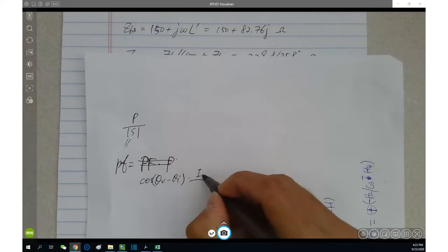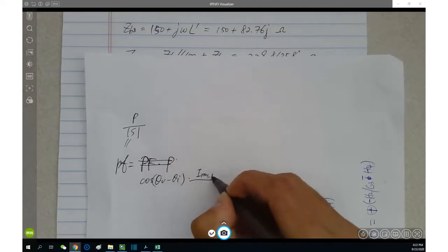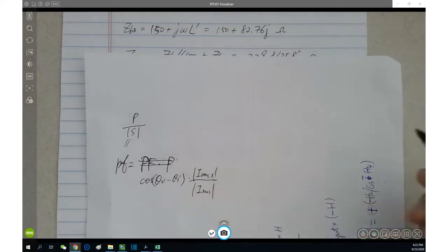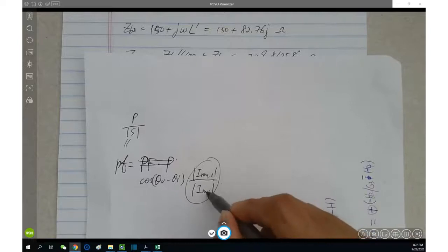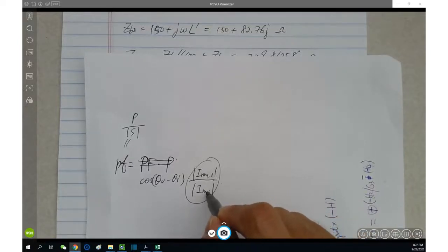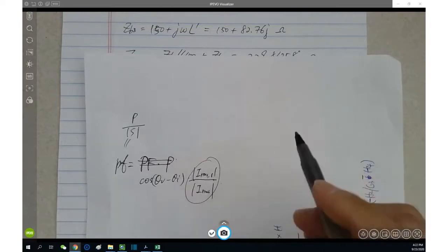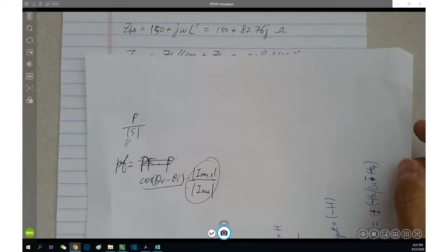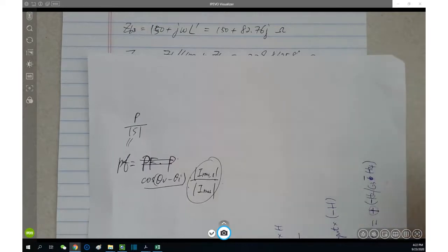The current RMS fundamental divided by the total current RMS. This is fundamental over the total RMS. This is the harmonics part, how harmonics play a role in the power factor. This is the phase-off. The product between the two.